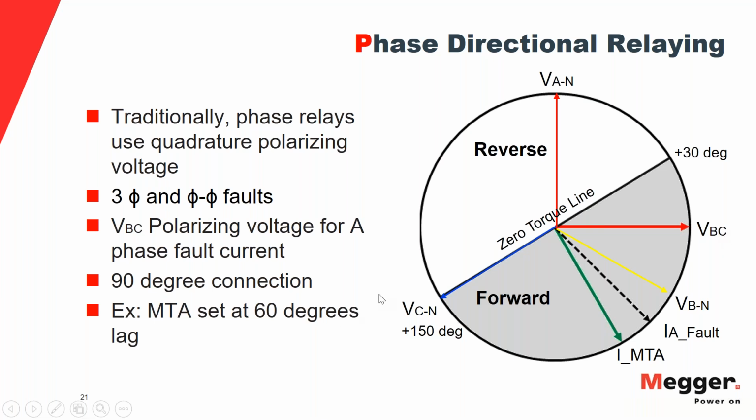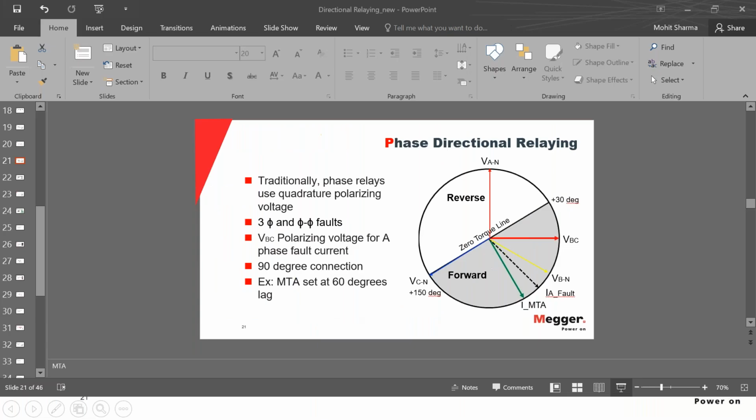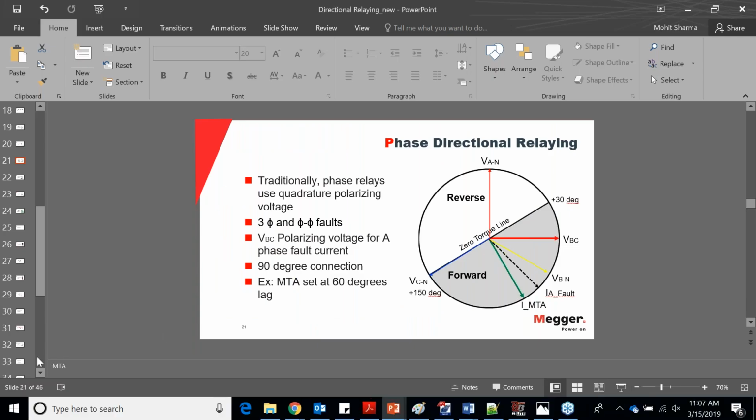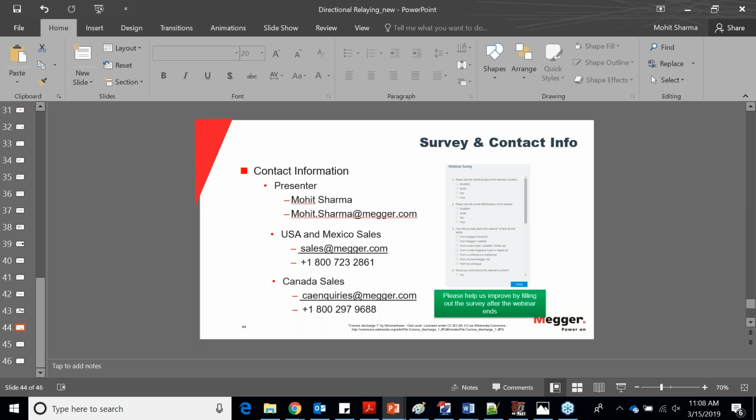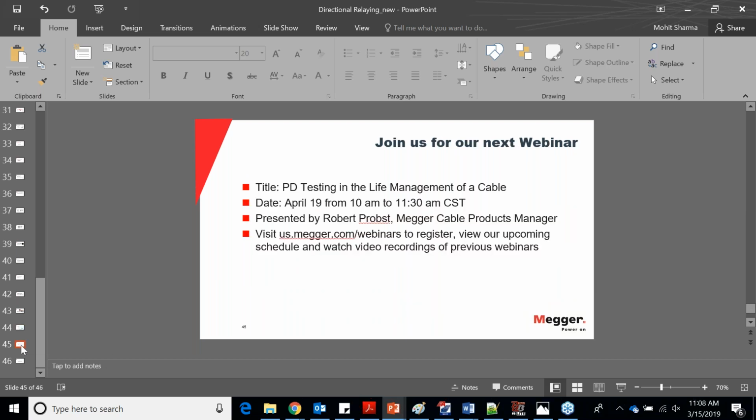All right. The next question is for Danabal. Can leading power factor currents, especially at low power factors, spoof directionality? It's a good question too. It depends on when the directional elements are used in generator protection. The possibility of maloperation is there. So we use reverse power functionalities to avoid this leading directional element operation. It is possible sometimes in generator protection relays, but in line protection, no, it's not.